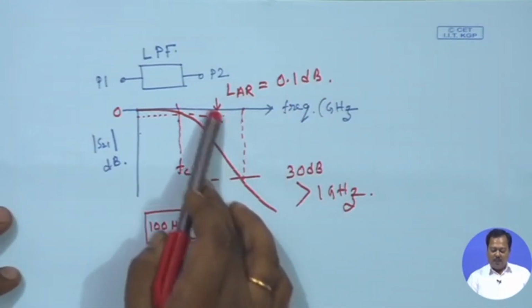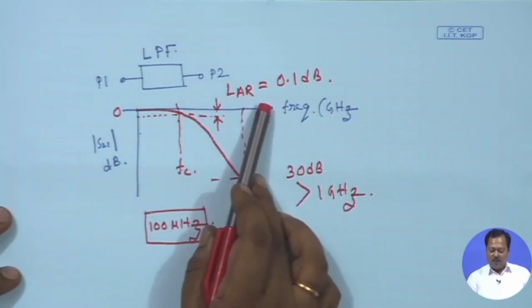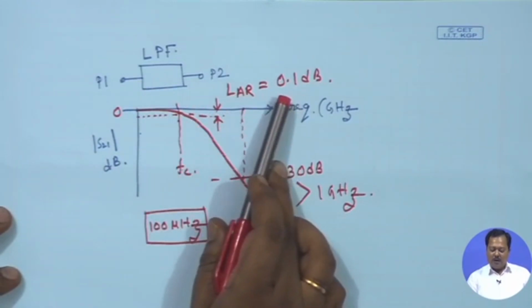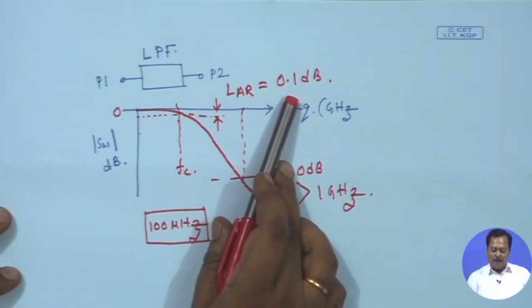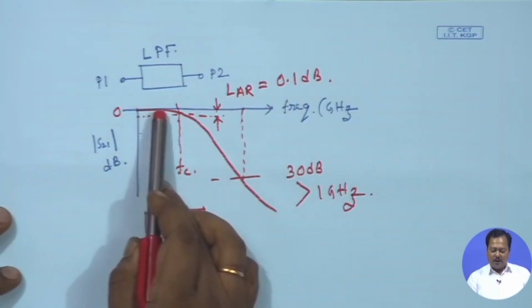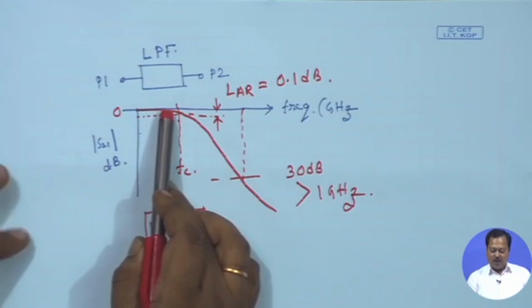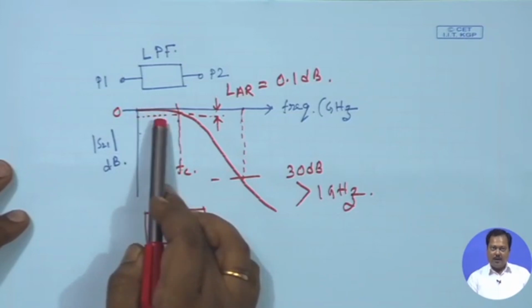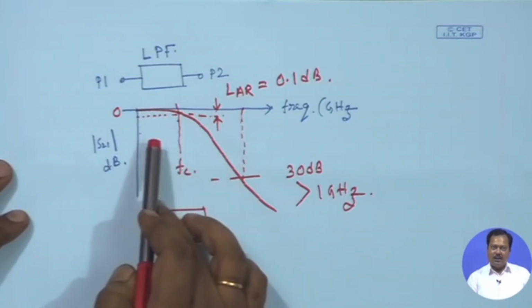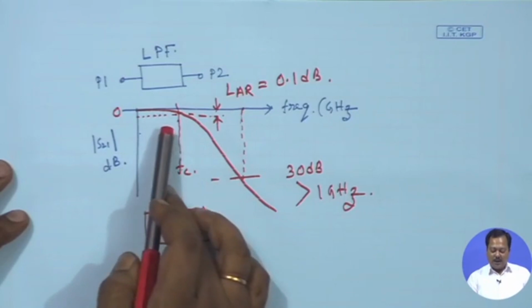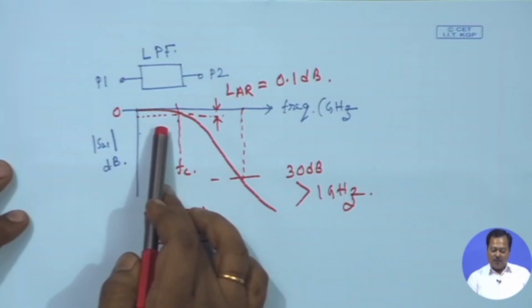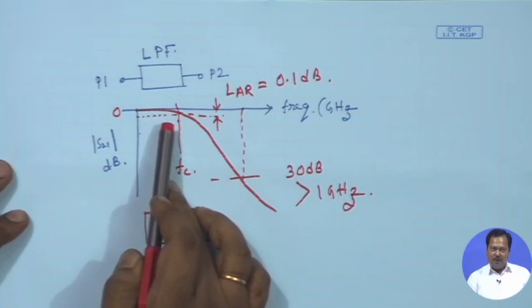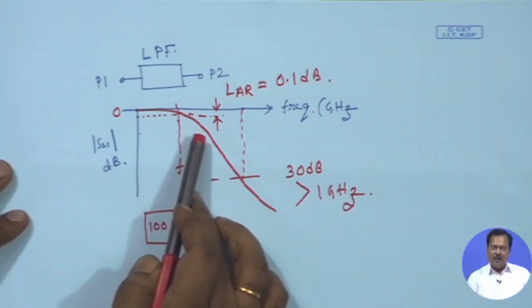Now, after fabricating this filter, whatever bandwidth I define, let us say 0.1 or 0.01, it can't be measured because of fabrication tolerance and also the accuracy problem of the VNA. This S21 will vary inside the passband, and this variation will be more than, let us say, 0.01 dB. So, it is really difficult to measure that 0.1 dB or 0.01 dB bandwidth of a filter, and practically we measure 3 dB cutoff frequencies. It is easier to measure.